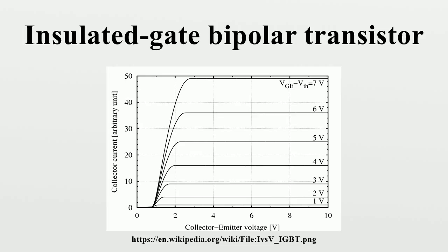The on-state forward voltage drop in IGBTs behaves very differently from power MOSFETs. The MOSFET voltage drop can be modeled as a resistance, with the voltage drop proportional to current. By contrast, the IGBT has a diode-like voltage drop increasing only with the log of the current. Additionally, MOSFET resistance is typically lower for smaller blocking voltages, so the choice between IGBTs and power MOSFETs will depend on both the blocking voltage and current involved in a particular application.